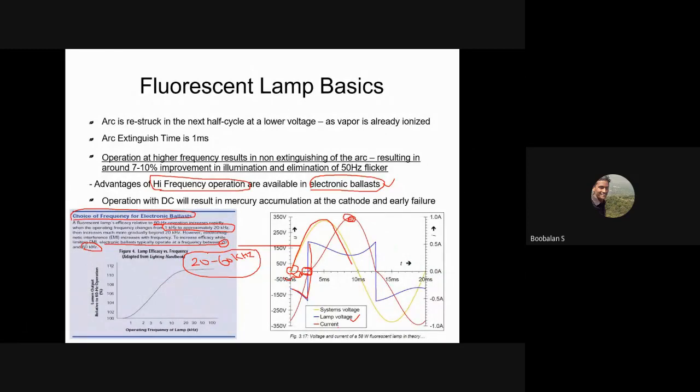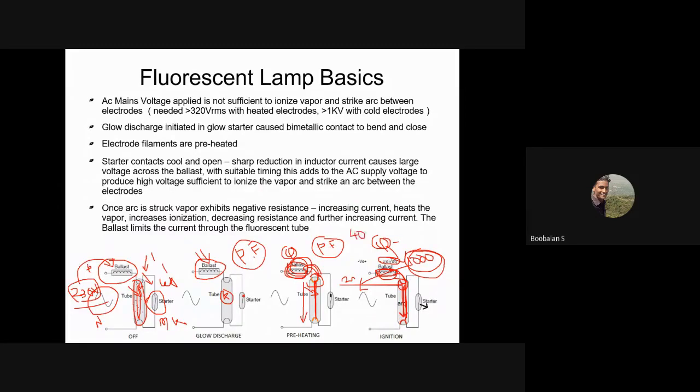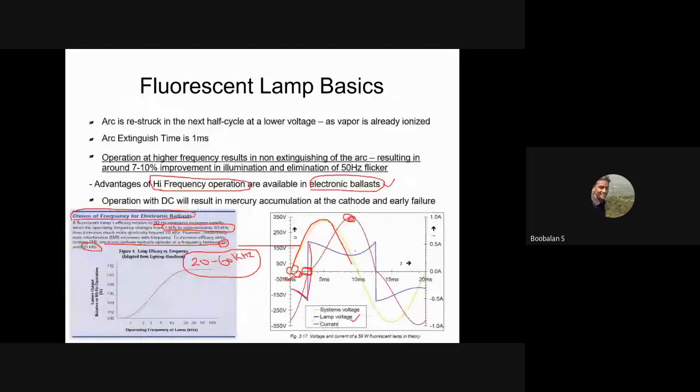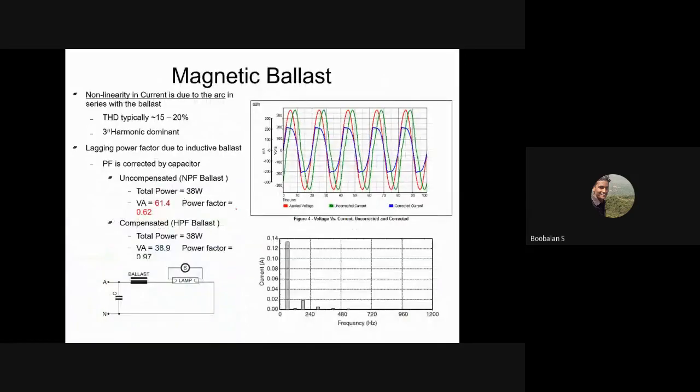If we use an electronic ballast, we are going to reduce the power. If you watch carefully, for example a 36 watt or 40 watt lamp, if you go to the market and look at a fluorescent magnetic ballast, there is a 40 watt bulb. Now with an electronic ballast it will be very low power, around 26 watts, below that. This is the total power; it will be below 26 watts.